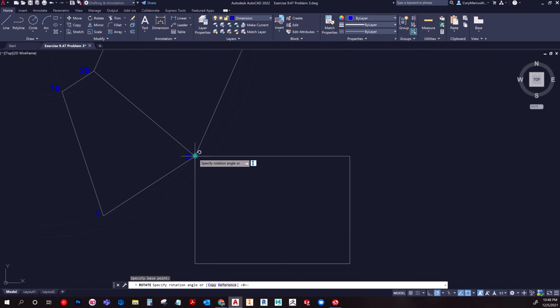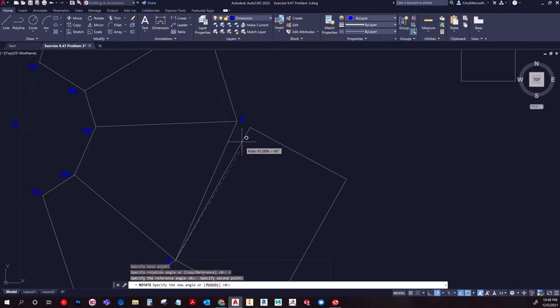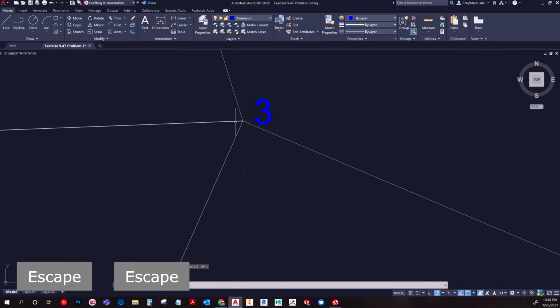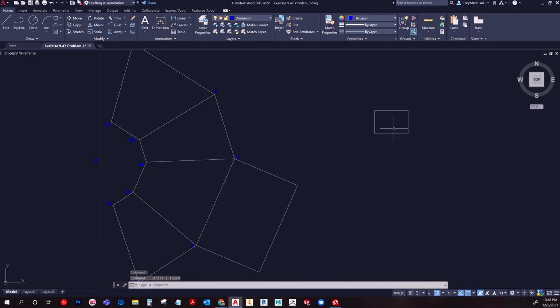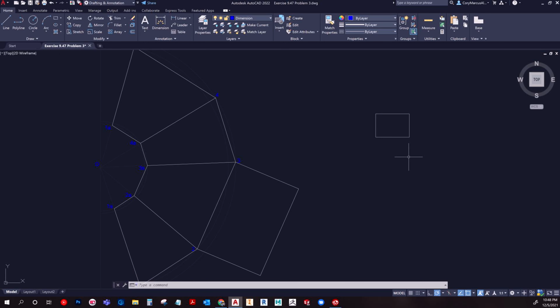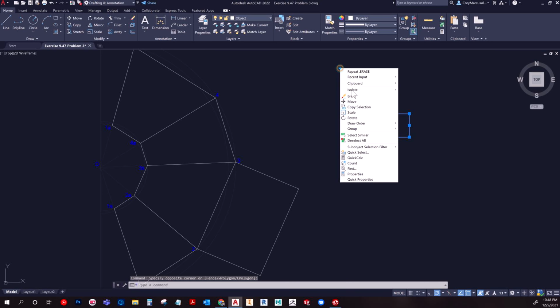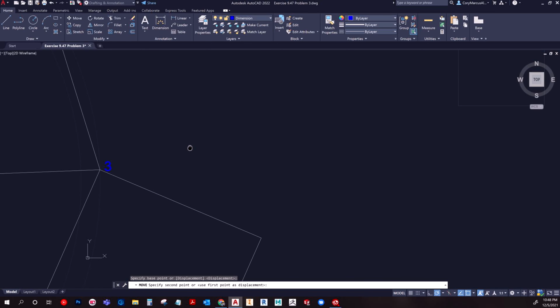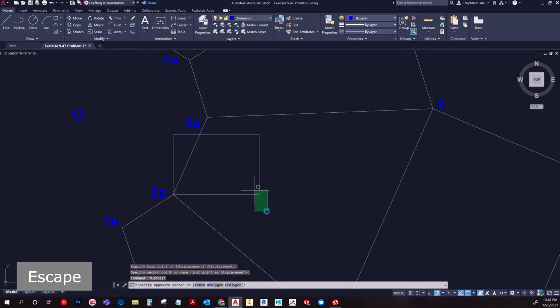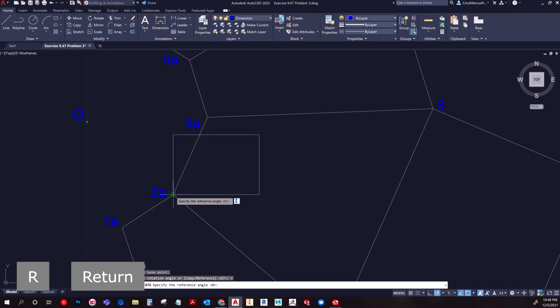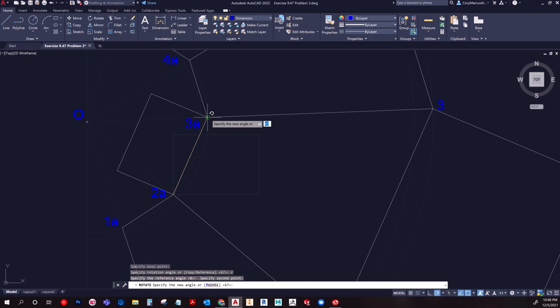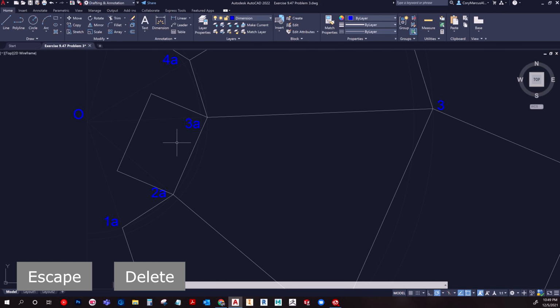So I'll do a base point, then we'll do reference. We'll drag the line and connect it. And obviously you'll know if it worked right if you don't have any excess. These edges meet perfectly. The vertexes are coincident. So we have done a good thing. And we'll do the same thing essentially, connecting to the same face over here. We'll just do that same little rotate trick. And look at that. That's nice.